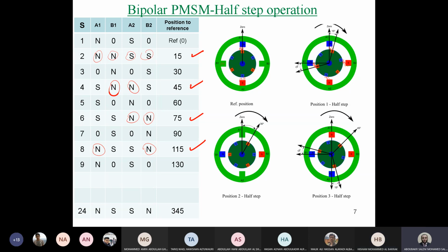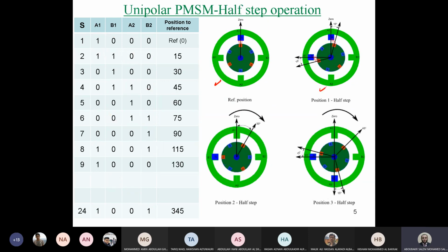For a unipolar motor, you have the rotor coupled from two sides at most. Right or wrong? For unipolar, if we return back again, we said the maximum power can be obtained if we energize two half coils. However, in case of bipolar, you can energize now the two coils together, and this will make bonding or coupling for the rotor from four sides, not only two sides.